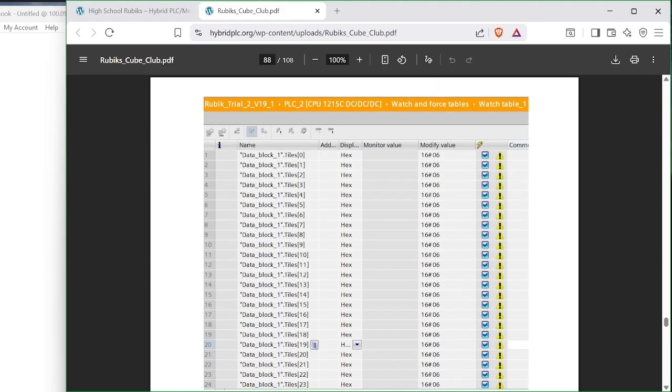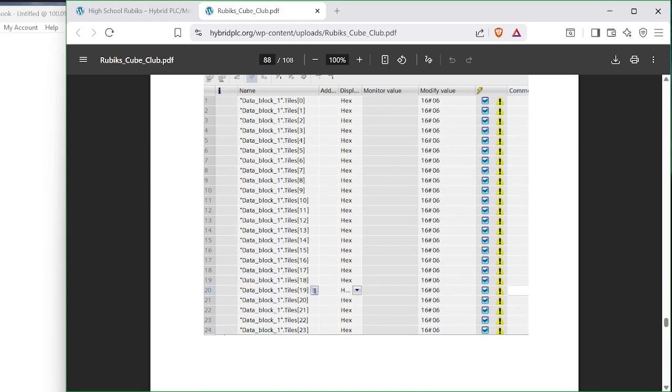Okay, that's the easy one. But now, what else do I have? With that array, how do I check that array to see if it's working or not? I have a watch table. And as I turn it, I see the colors moving in the watch table. So positionally, as I do a 90-degree turn, I move those numbers in that watch table to their new position, and I see that with updating the watch table. So I can check it very easily by executing the watch table.